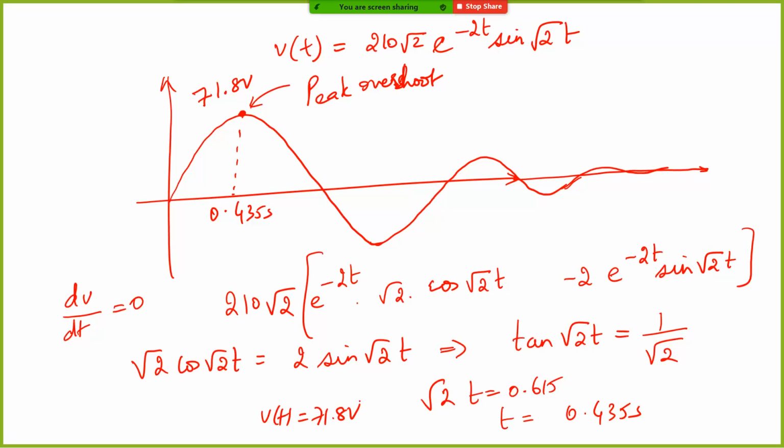So this is the way that you can characterize it. So is it clear? If your system is underdamped, it is just going to ring for a longer time, and if your alpha becomes lower and lower, it is going to keep ringing for a much longer time. And so if this is your V max, you can find out the settling time. Can we determine the settling time?